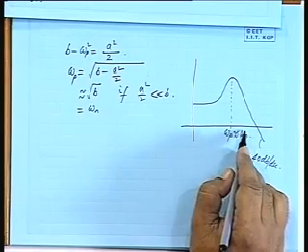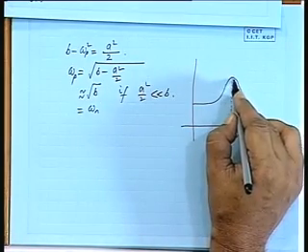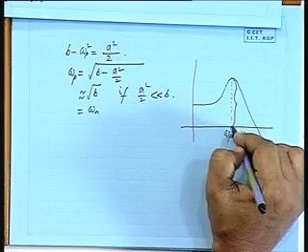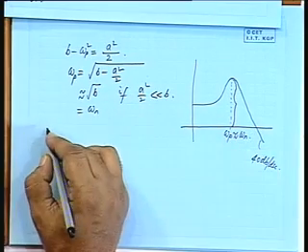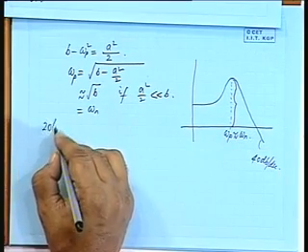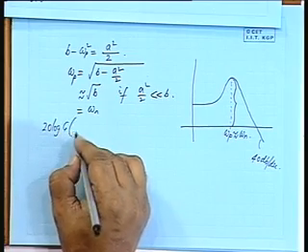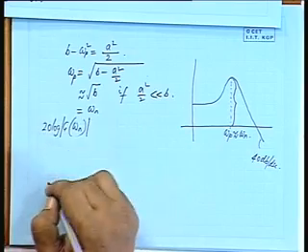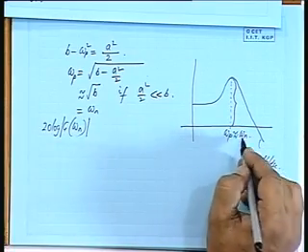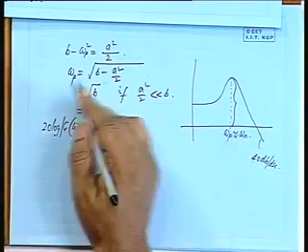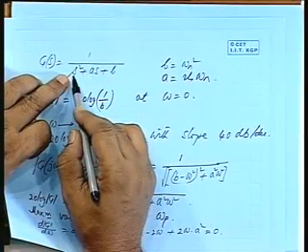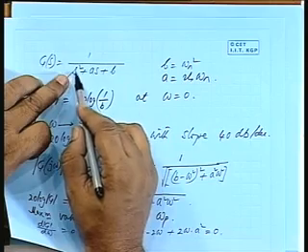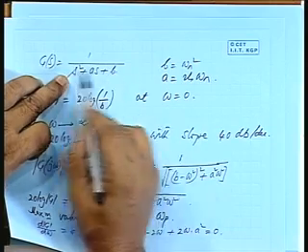At this value omega n, how much is this height? What is the value of 20 log of g at omega n? Omega p is close to omega n. So, if I put just omega n, b minus omega n squared will get cancelled.